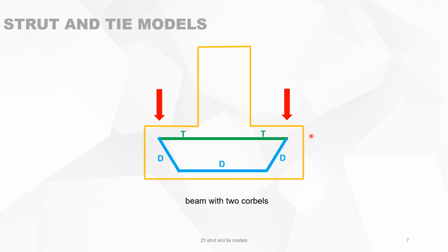But it's not all, because now you have to tie this in with the main body of the beam. And now you can calculate the tension in the ties and the compression in the struts, and you can calculate the needed reinforcement.